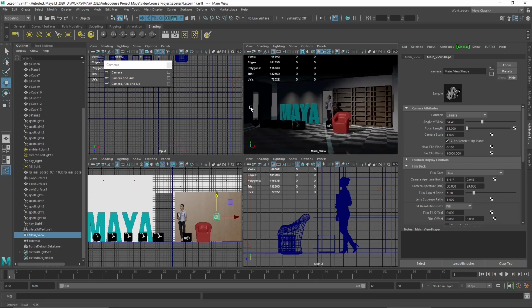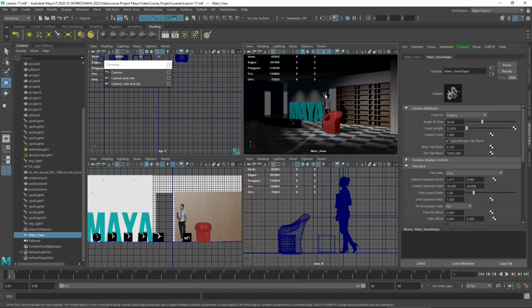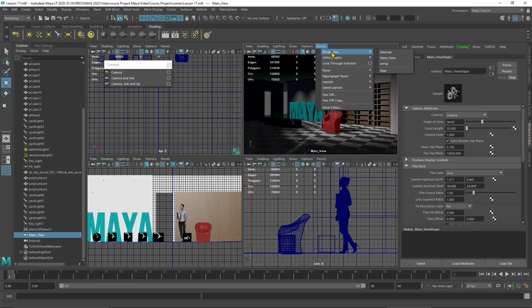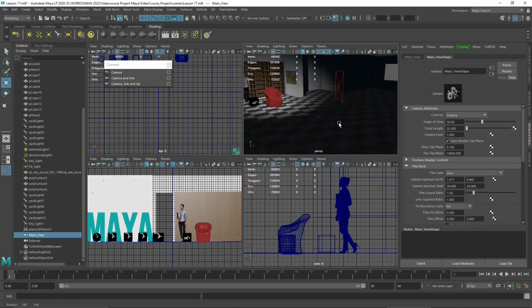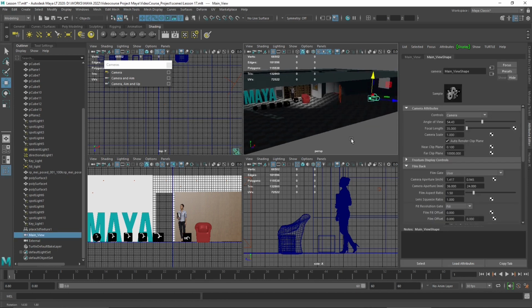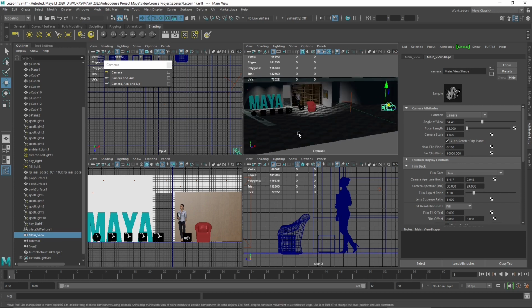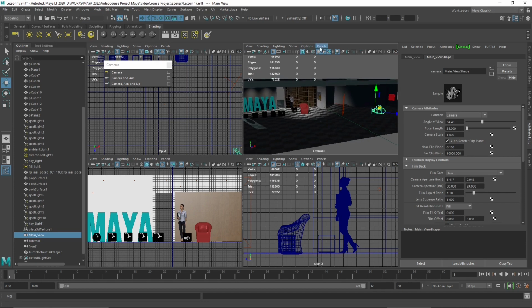We are changing the position, we are changing the rotation, and not the scale, because we don't need scale. So you can see that I have just changed the position of that initial camera. Or I can do that in the viewport using the move and rotate tools. But I always then need to check the final outcome by going inside the view in the perspective there.